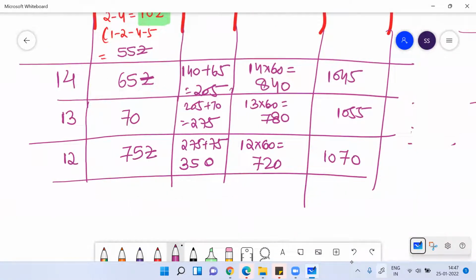Okay, max to max, I can reduce it for 12 days. So here, you notice that the minimum duration for my work is 12 days, and after that no more crashing is possible because all the activities of the path 1 to 3, 3 to 4, and 4 to 5 are over. So your minimum duration was 12 days, and the total cost associated with that was 1070 rupees.